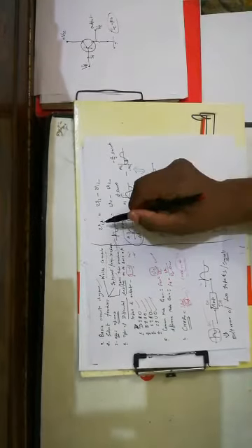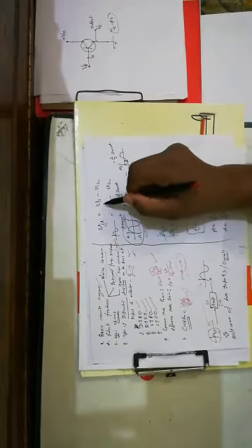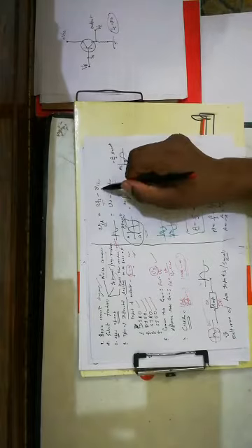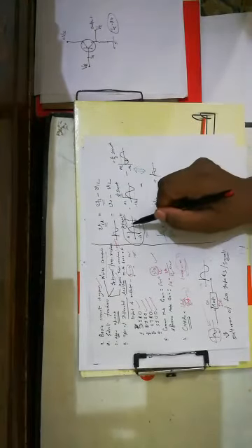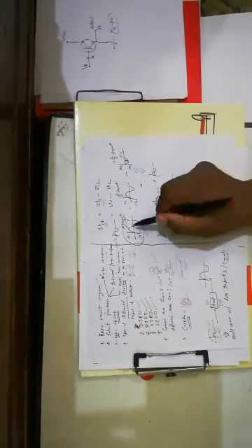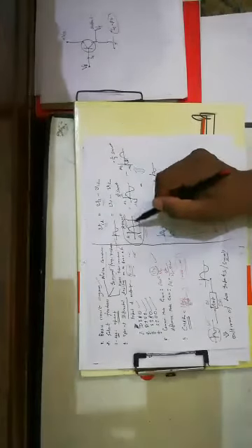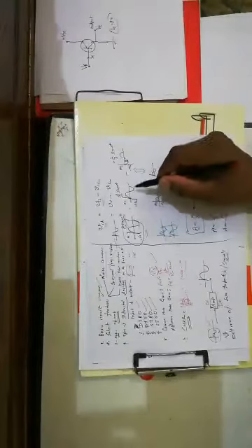As we know, the input of the differential amplifier is the difference of two signals. Let us suppose I want to give this signal as an input, a signal A sin omega t. A is the maximum amplitude on the positive side and minus A is the maximum amplitude on the negative side. This is one method that I am telling you.